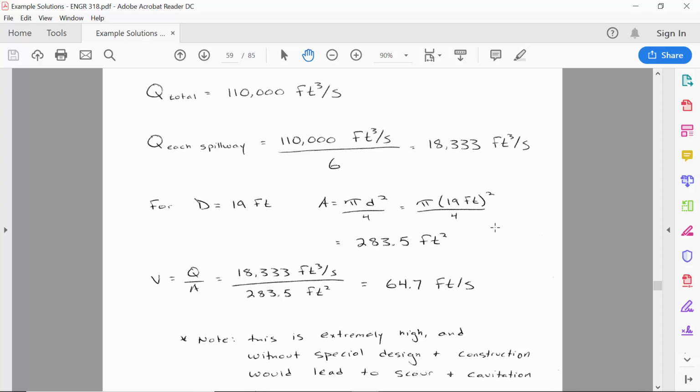What happens to the pressure of a liquid when the velocity increases? What does Bernoulli's equation say the pressure response to an increase in velocity is going to be? The pressure decreases. Right. So if we wanted to apply Bernoulli's equation between, let's make this location 2 in the pipe, and location 1 is in the river upstream of that inlet pipe.